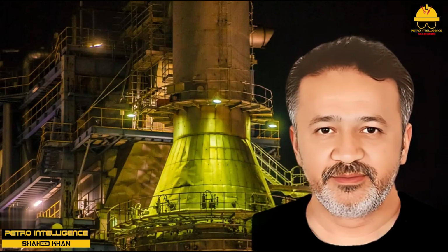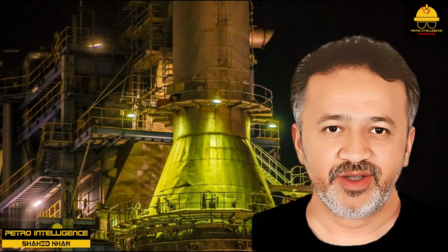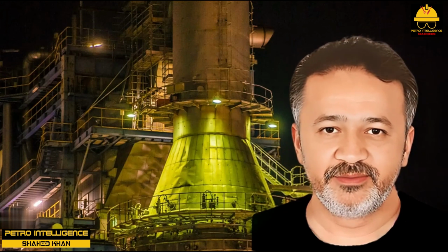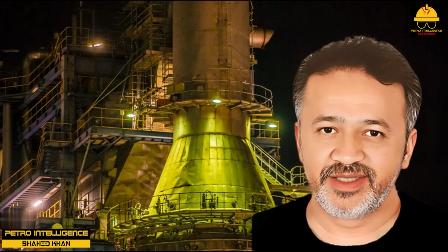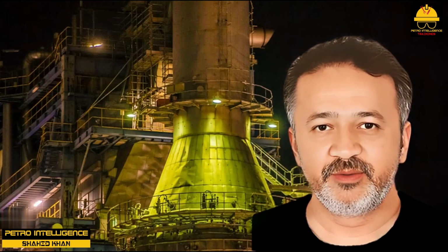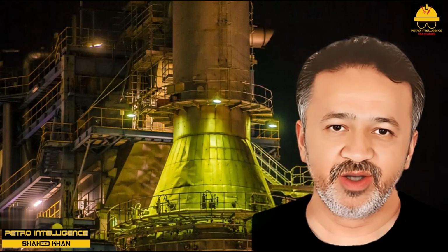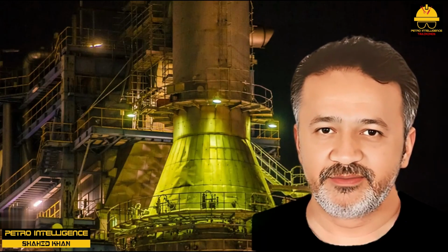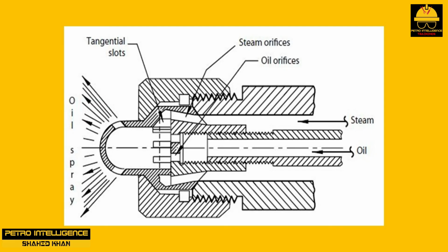Oil burners. In the United States, oil firing is uncommon. In Europe, it's pretty standard. Most oil-fired burners use atomizing steam to produce a large surface area of the oil exposed to the combustion air. In the steam atomizer shown in the picture, jets of oil under pressure meet the spinning jets of steam under pressure in the mixing chamber. A mist of oil and steam is discharged into the furnace.